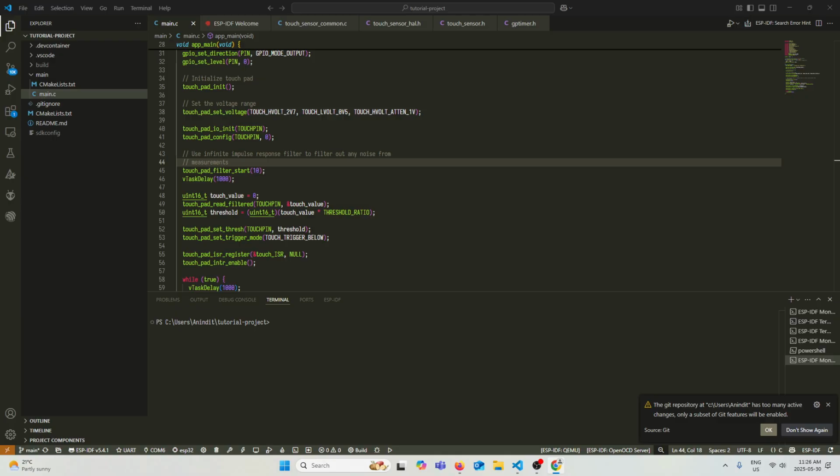Now I will move to some concepts you should know when working with ADC. The resolution of the ADC provided by ESP32 is 12 bits, which means that the measured voltage level is between the value of 0 and 4095. However, you can change the resolution or bit width used in your application from 9 to 12 bits. The attenuation of ADC refers to the voltage scaling factor that can be used when measuring voltage levels beyond 0 to VREF. VREF is the reference voltage used internally by the ESP32 ADC. It differs from chip to chip, but the median is 1.1 volt.